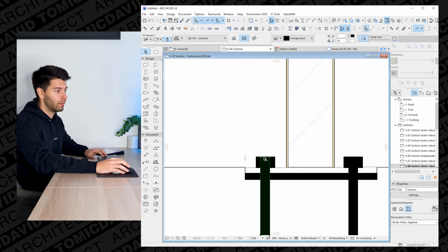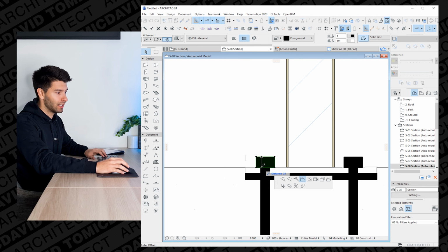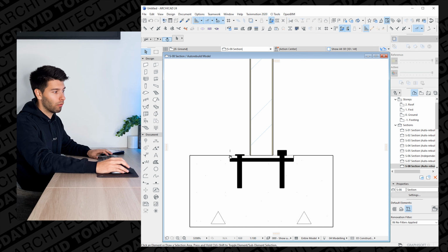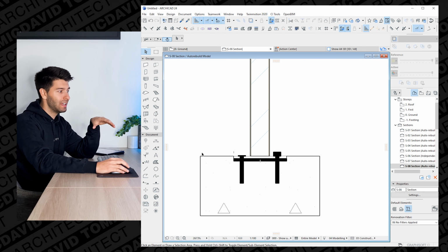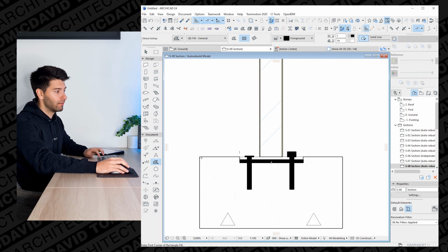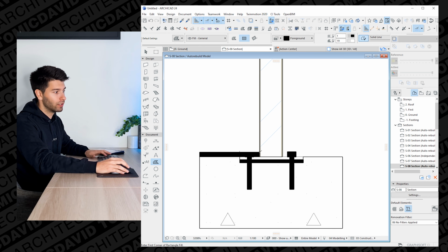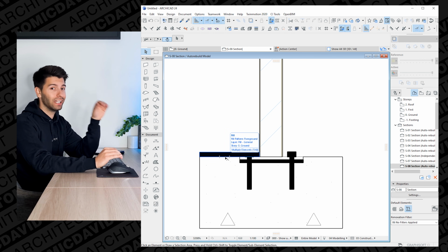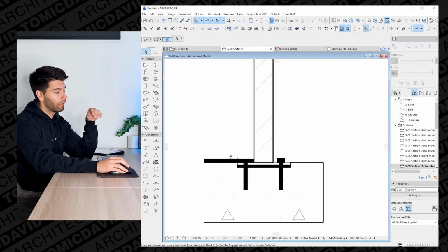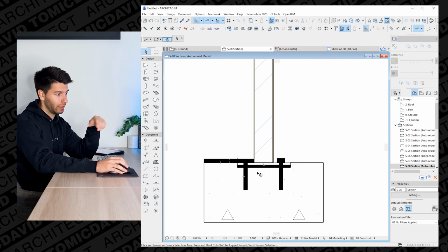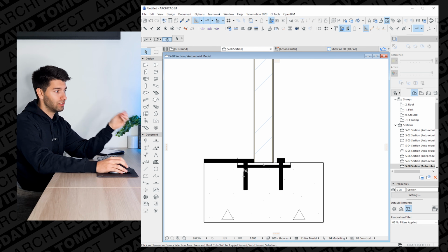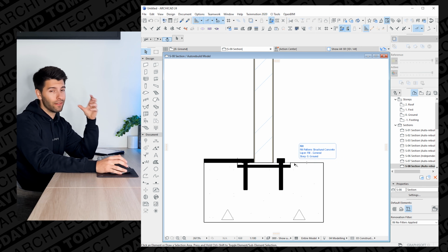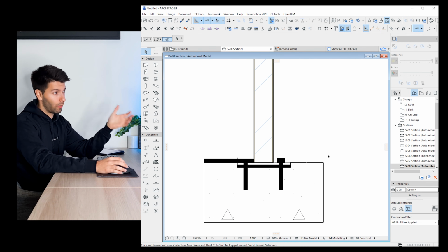We can get flathead bolts, we can then drag that down something like this, have very small flathead bolts so it isn't seen, and then potentially if you have some sort of sheeting covering over the top, be it tiles, be it carpet, you might be able to hide that if the bolts are good enough and you actually detail it properly. But without drawing this sectional detail, you'll most likely have a very ugly connection from an architectural point of view.